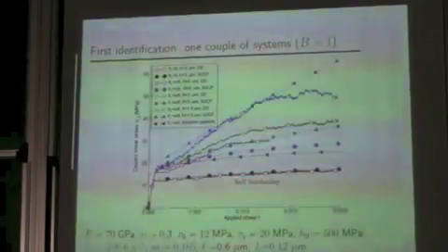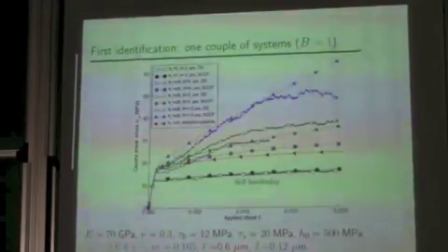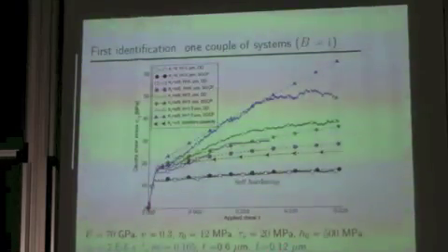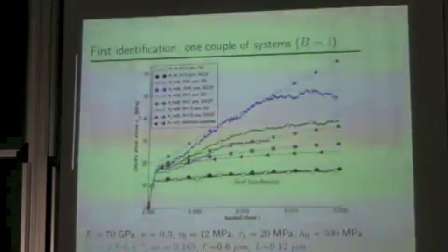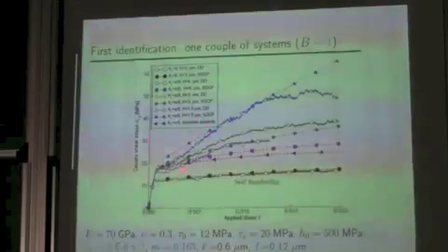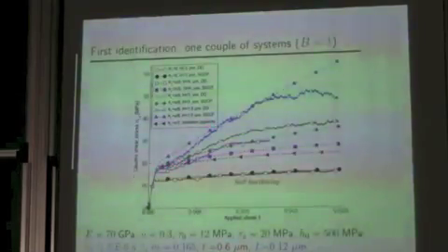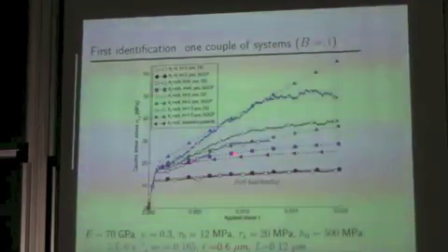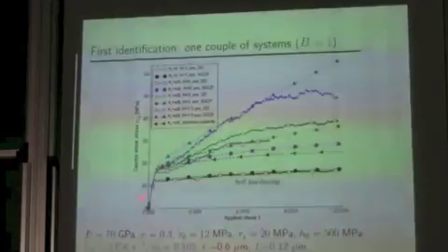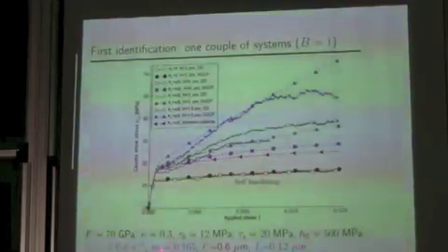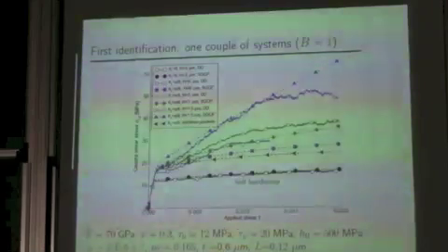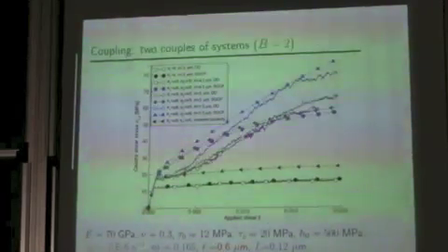which is quite good because the dislocation spacing at the end of the analysis is 0.1, and so we wanted to keep these two parameters, the rate sensitivity parameter and the dissipative length scale, as small as possible, but we couldn't go lower than this. The worst part of the comparison is just after the yield stress, because in DD many sources of dislocation just activate, so there is this decrease, while the crystal plasticity curves are not as straight as they could be if we could decrease these two parameters. But we cannot, because otherwise we don't converge.